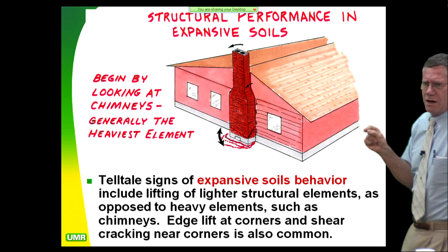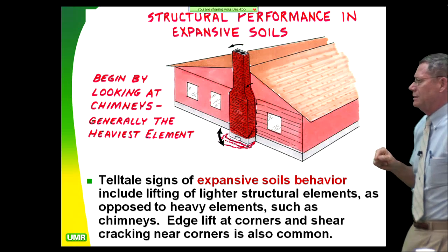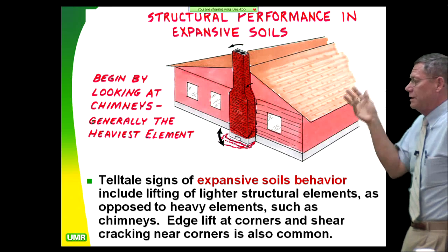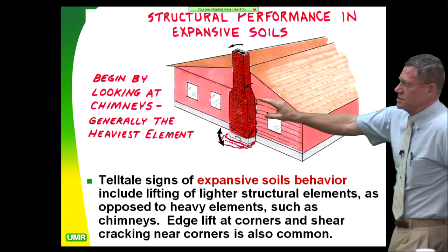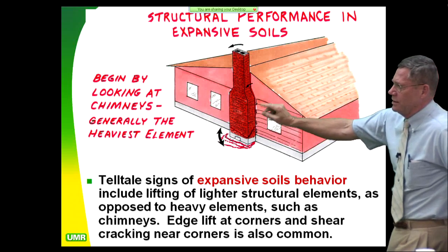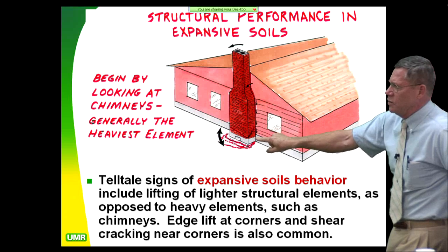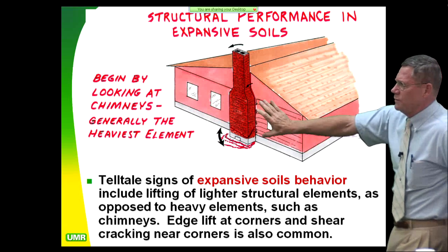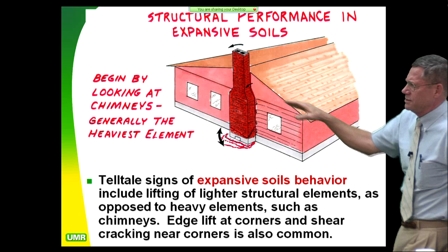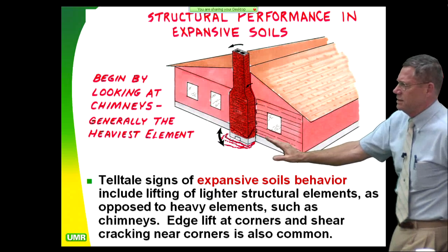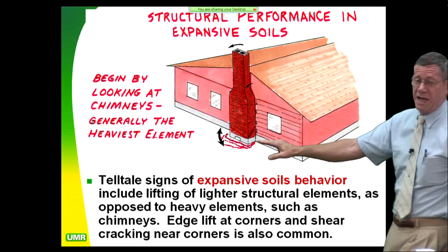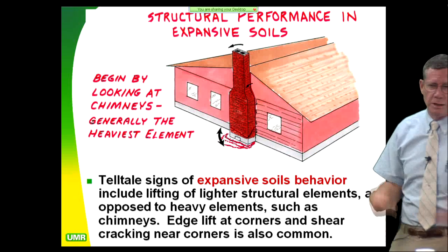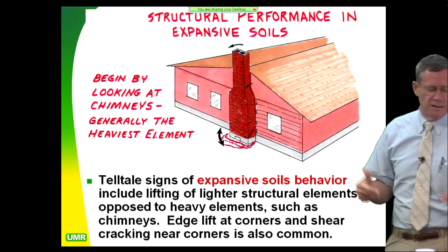Now, word of caution. Wood shrinks in cross grain significantly: 6% in cross grain over a period of years, and 1.5% in longitudinal grain. So if we look at an older house, these wood elements are going to shrink, and you're going to tend to see movement here that's due just to wood frame shrinkage, especially if you've got double headers on the top plates and on the sill plates. And so it's not all due to expansive soil necessarily. You do have to look at the framing system that they've used there.